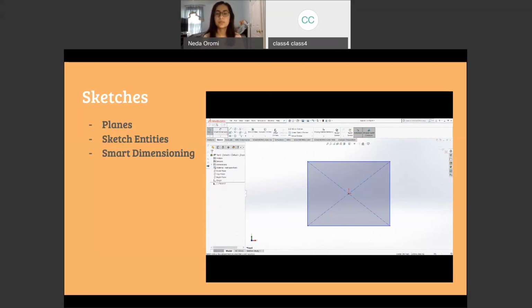That's where you put measurements to the sides. You can also change which system measurement you're using. You can go from imperial to metric, but in this example, we just stick to imperial. And if this ever happens where everything goes gray and nothing's visible, just go back to your toolbar and go back to edit sketch. So now we're going to dimension it.